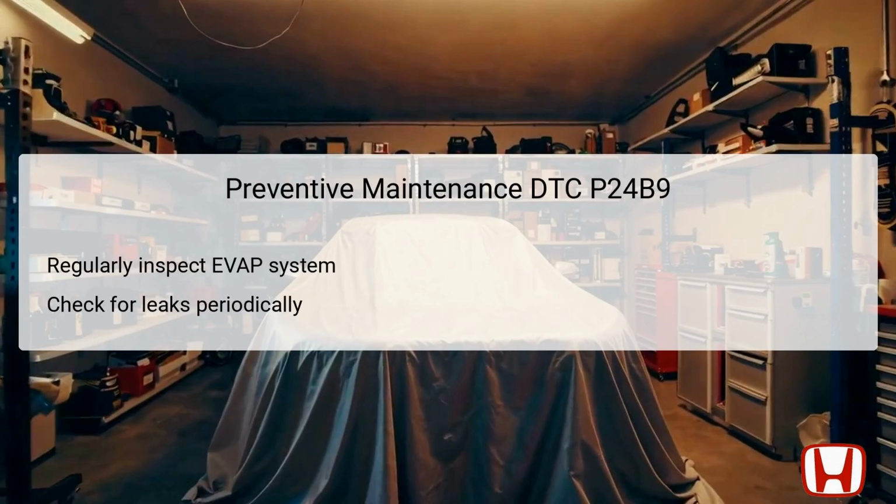To prevent future occurrences of DTC P24B9, routine preventive maintenance on the EVAP system is highly recommended. Technicians and vehicle owners should schedule regular inspections, focusing on hose integrity, the condition of filters, and ensuring that all components are sealed properly.